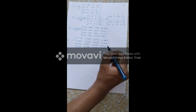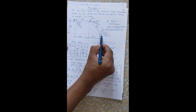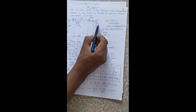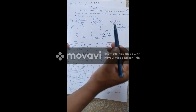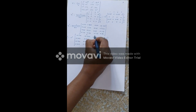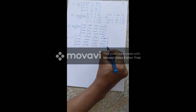You can observe that element 2 is made up of node number 1 and node number 3. So while writing the displacements, it will constitute Q1, Q2, Q5, Q6. That is the reason why we write 1, 2, 5, 6, 1, 2, 5, 6.